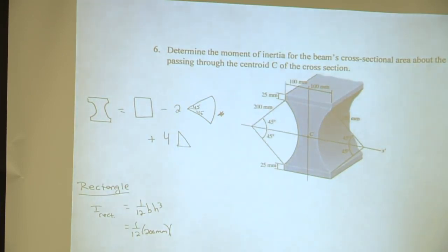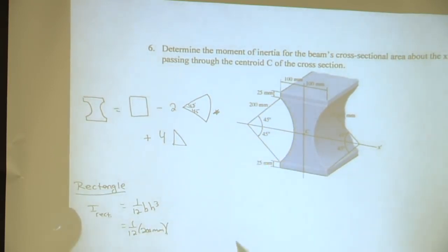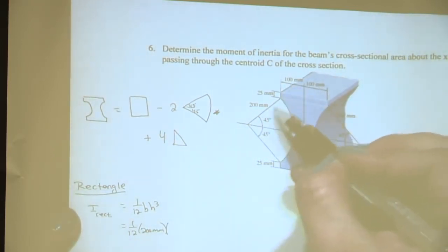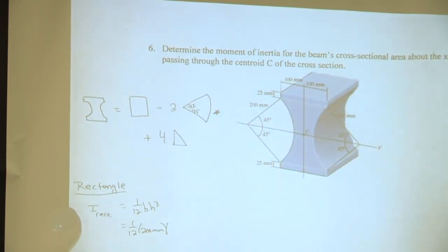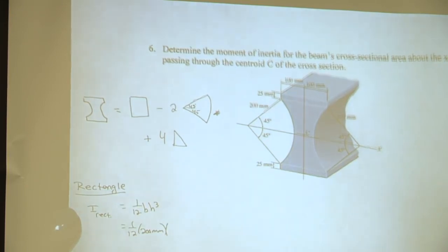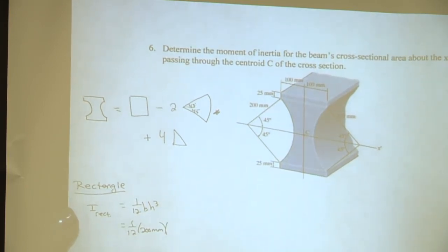You have to start from the triangle, right? So do we actually have a value for the height listed there? No. So how do we find it? By using a triangle. Okay, awesome. So we can use this right here. We know that this distance right here is 200. So how do we get the vertical distance? Sine. So we do 200 sine of 45. Now why is it sine, not cosine? Because you want the height.